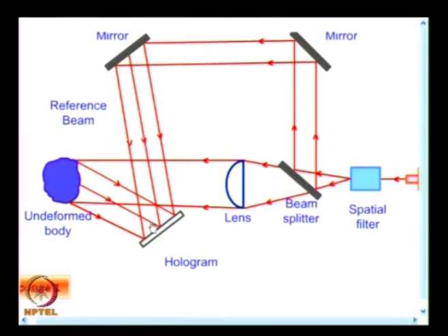One of the techniques people used was, they wanted to record multiple images with known phase shifts, because in order to resolve the ambiguity in fixing the sign, fixing the integer fringe order, they had recorded multiple images, and the whole approach was processing the intensity information.